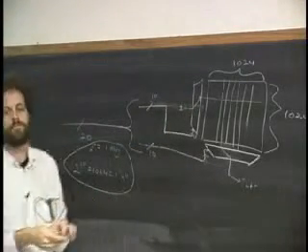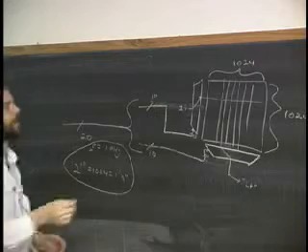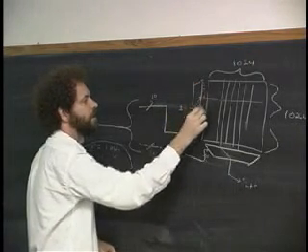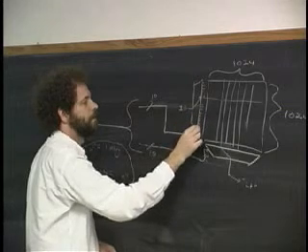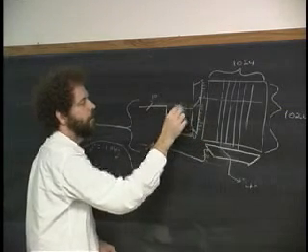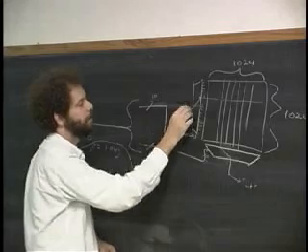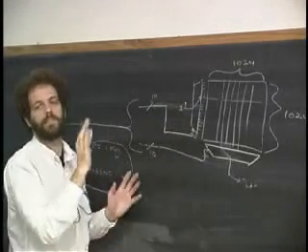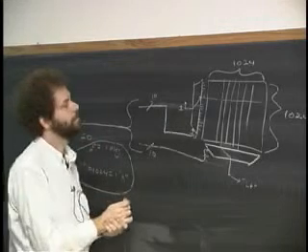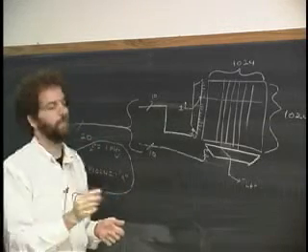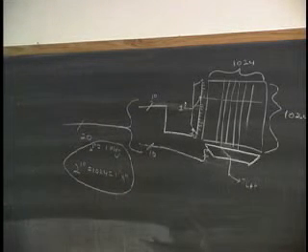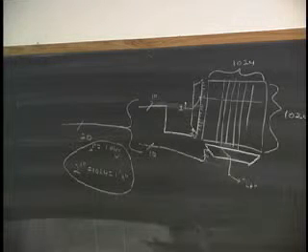What does the 1 correspond to there on the left side? The 1 says this is the one that I'm going to choose. So this is a 1, and all the other ones are going to be 0. If you remember, it's not a wire coming in with a value 1, it actually is a constant 1. If it was a voltage, I would say I pull this voltage up to a positive voltage all of the time. It's the constant 1. Okay, so that's like a read enable. Exactly. Okay, but we'll talk about exactly what this thing does. And this is going to be a little bit of a hint into the circuitry that's going to be involved in storing each one of these bits.